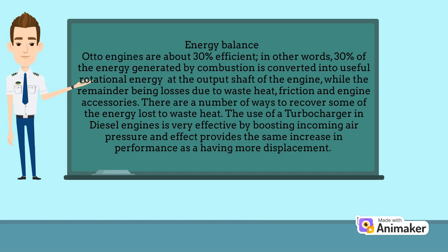Energy balance. Auto engines are about 30% efficient. In other words, 30% of the energy generated by combustion is converted into useful rotational energy at the output shaft of the engine, while the remainder is lost to waste heat, friction and engine accessories. There are a number of ways to recover some of the energy lost to waste heat. Use of a turbocharger, as in diesel engines, is very effective, boosting incoming air pressure and in effect providing the same increase in performance as having more displacement.